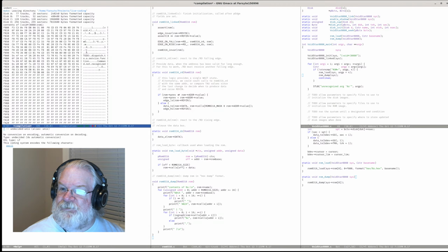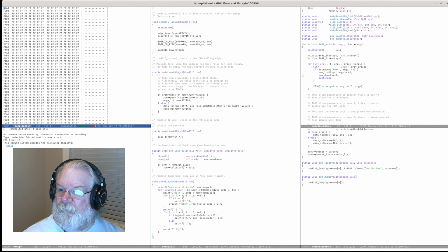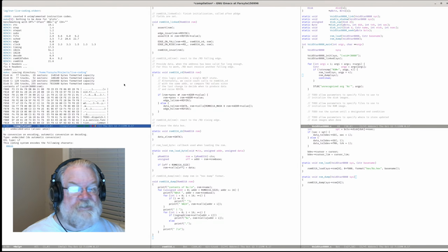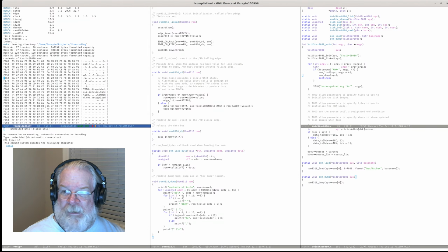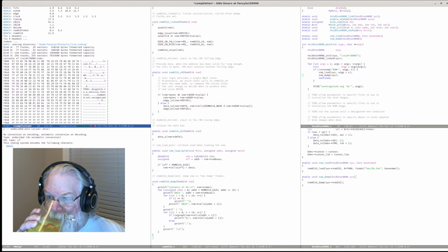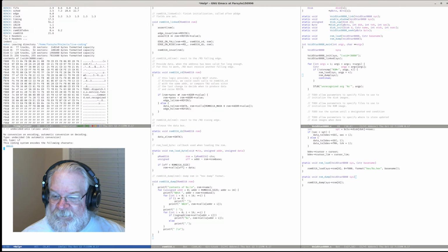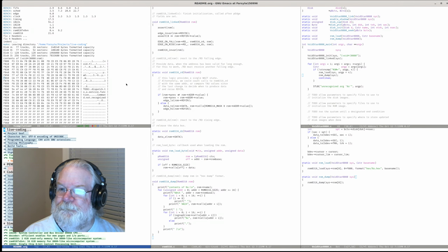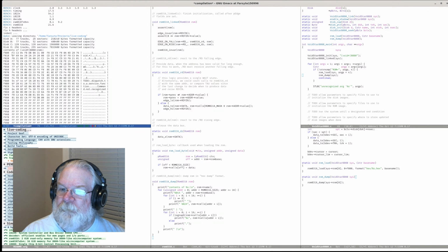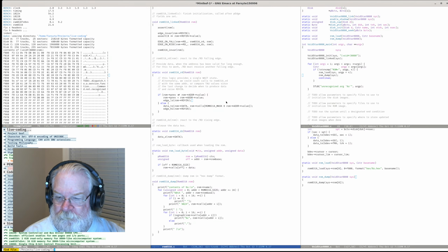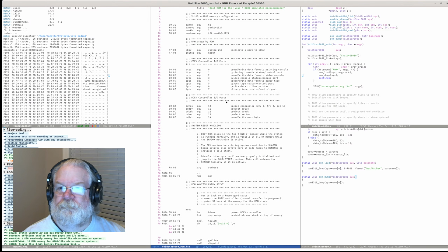And here is what is now inside the ROM. You see that we're just barely tucking in. This means that we can add quite a lot in the way of commands. I'm thinking things like dump address ranges and set memory and jump to things. But does it match our listing? So what we should see is F3, C3, 04, F8. That looks good. So I believe that we have got the right data into our ROM.